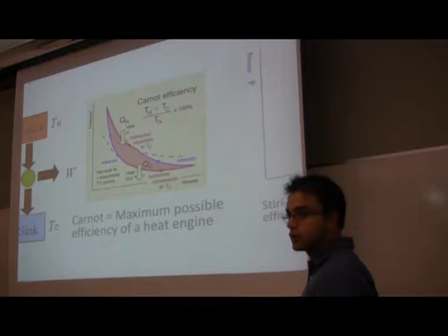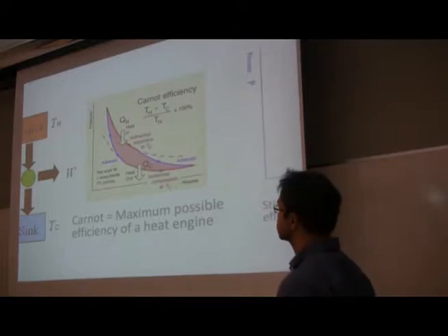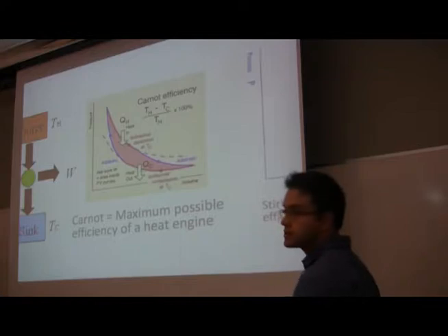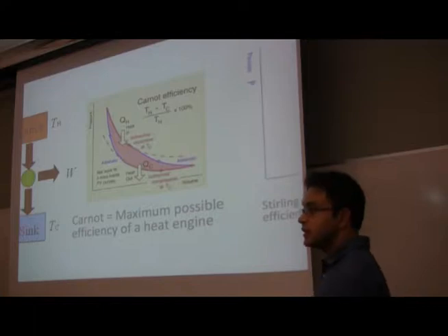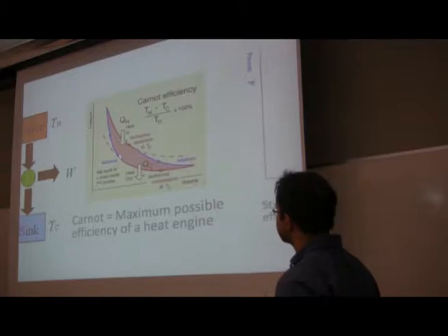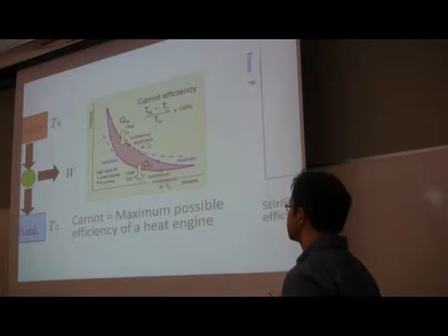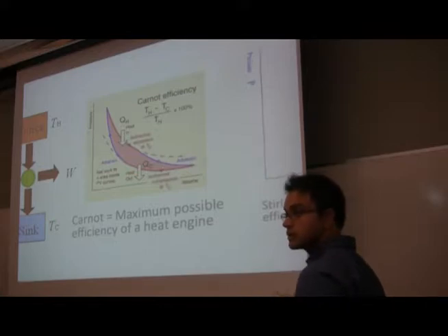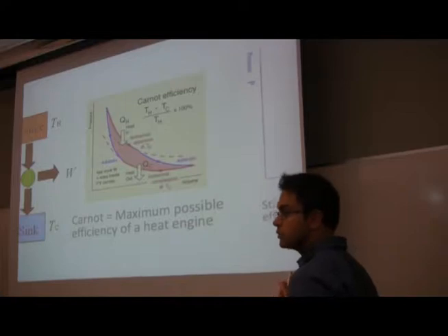For solar thermal and, in general, thermal applications, the engine performances are defined based on what I call pressure-volume curves, because as you remember, there are fluids that change their pressure, change their volume, right? They expand, run something, and so on and so forth. So that's what those are typically drawn on. So you have a situation where your volume decreases, pressure increases, so it's compression. And then you have expansion, volume increases, pressure decreases. Okay, and then the same thing happens. So that's a cycle. It's a reversible cycle. Okay, it's an important criterion for the Carnot engine.